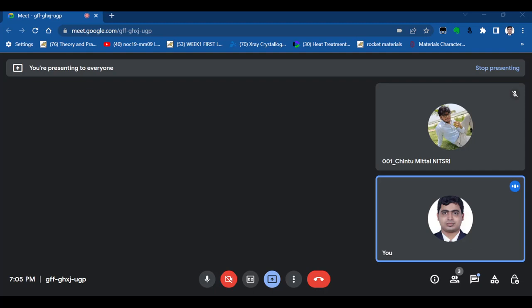So forget about this. This is a geometric factor. Depending on whether the crack is a surface crack, this is something close to 1.1 for surface cracks, and 1 for center cracks. As you have considered the same crack geometry here, forget this. So we have to consider these three only. Sigma applied is same for both cases as it is given in the question. So this pi is also constant.